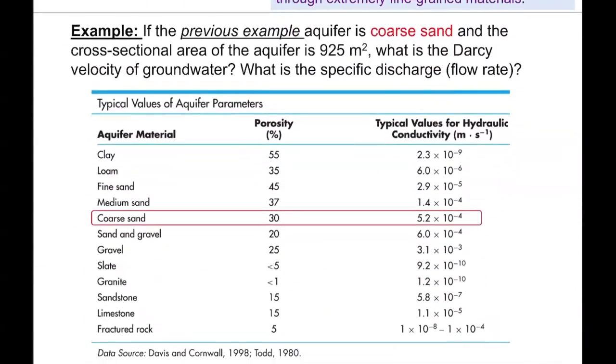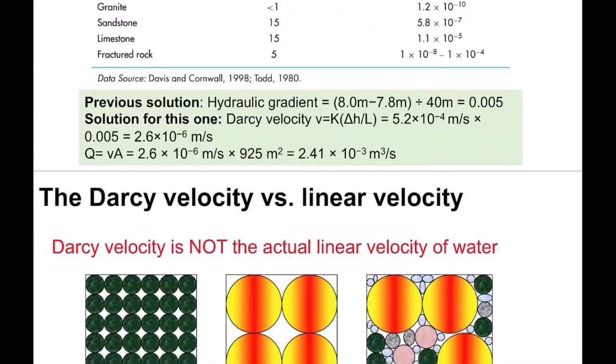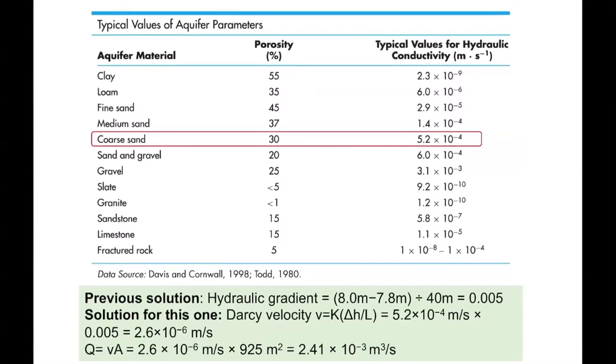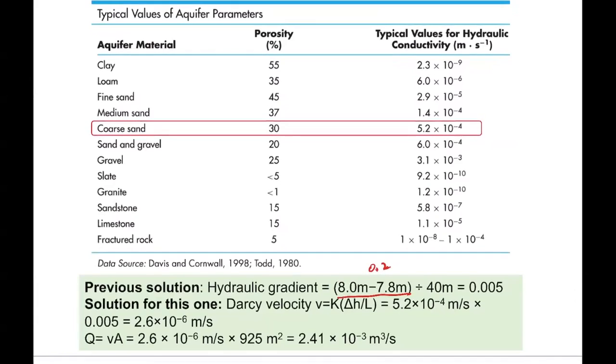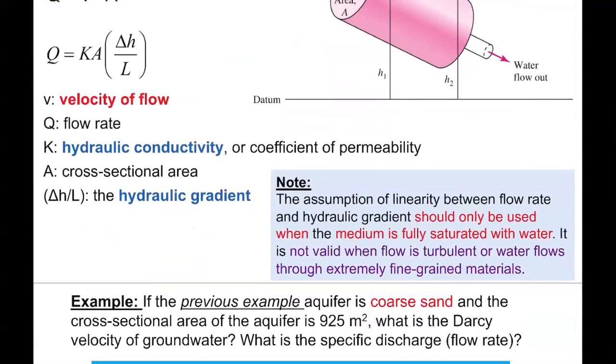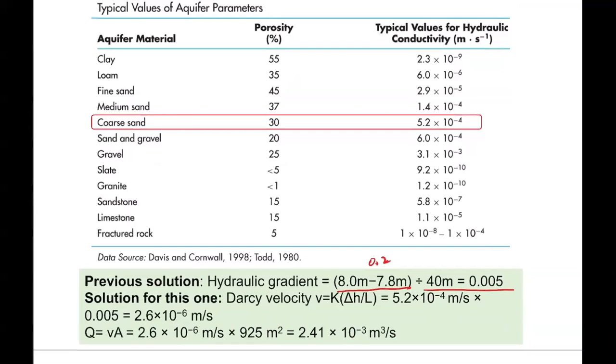very straightforward definitions. For example, if we're talking about that two well system again, you remember that 0.2 meters of the height difference, divided by 40, is the hydrologic gradient. So we can use Darcy's law. Basically this is called Darcy's law to calculate the velocity, right?